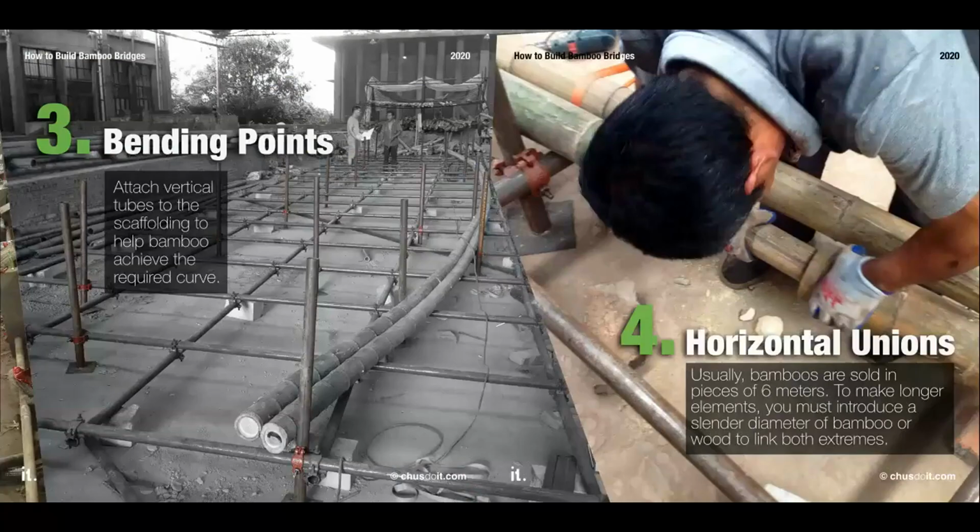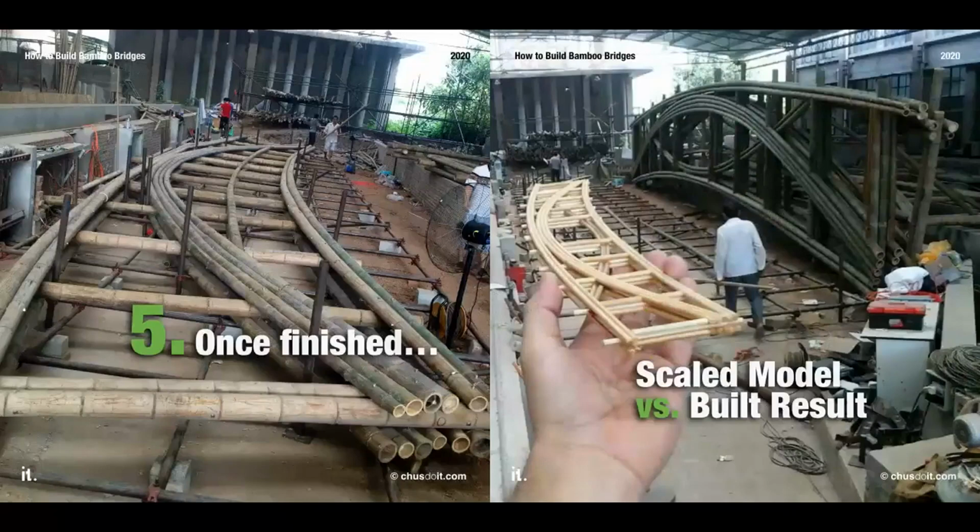Number 4. Horizontal unions. Usually, bamboos are sold in pieces of 6 meters long. To make longer elements, you must introduce a slender diameter of bamboo or wood to link both extremes. Number 5. Once finished, lift it up. Now you can compare it with the scale model.